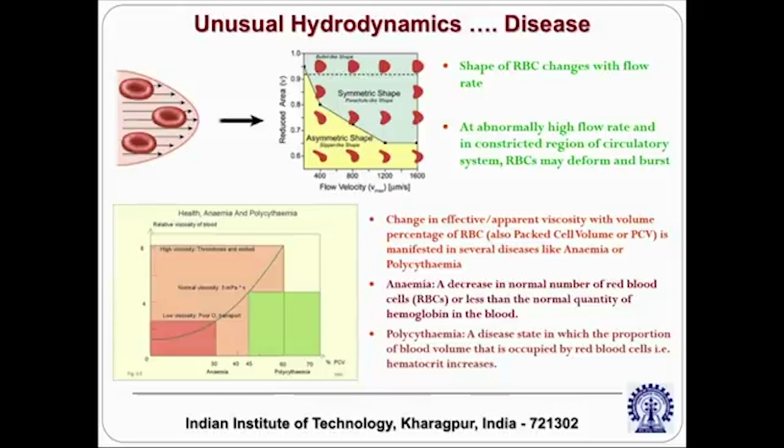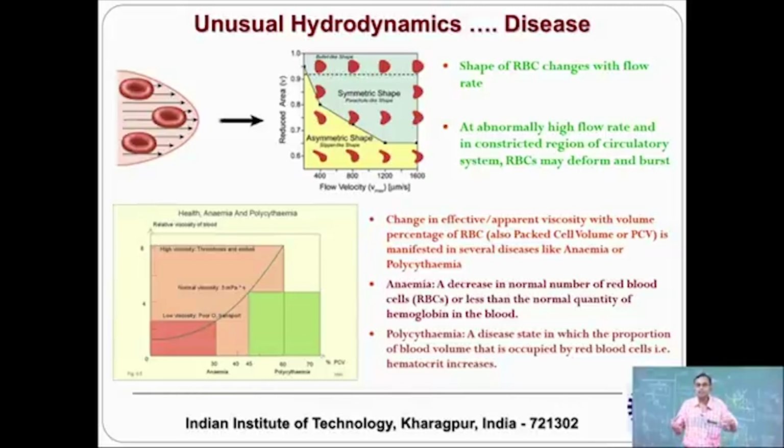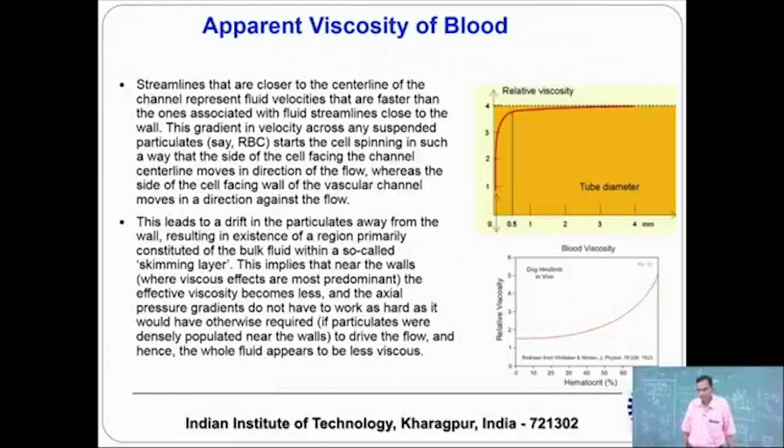Now, the hydrodynamics of blood as it flows through a microfluidic channel may be affected by certain diseased conditions, but even without that, a very important aspect which I want to highlight is the Fahraeus-Lindqvist effect. So, what is this effect? If you look at the top graph in the figure, you will see that as you reduce the diameter of the blood vessel, the apparent viscosity, instead of increasing, actually reduces.